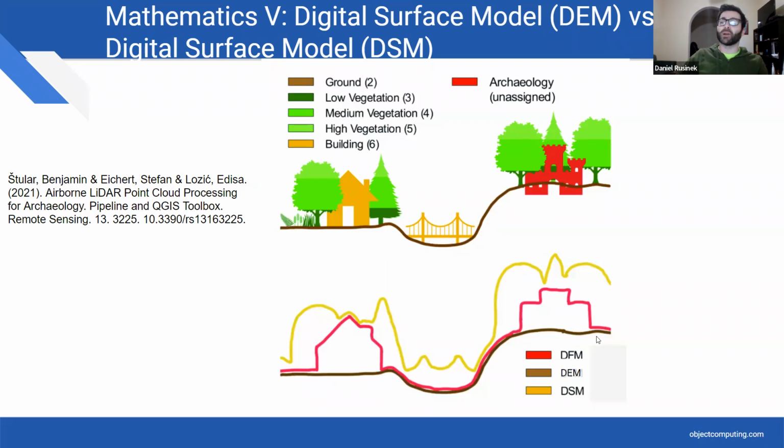So you pretty much get a bare earth model, what everything will look like with no cover, no trees, no buildings. And that can be very useful for geologic studies. That can be very useful for probably ballast management. And then if you use all the returns, or only the first returns, you get a digital surface model, which is an estimation of the entire surface, including all of the trees. And for vegetation management, that's what you're going to want to go with.